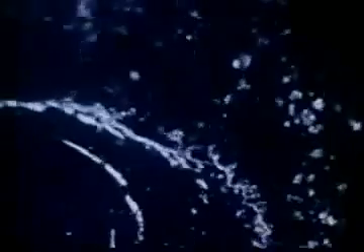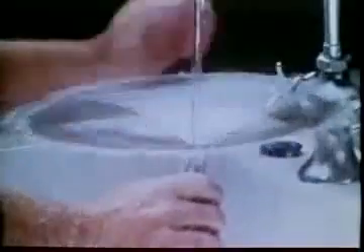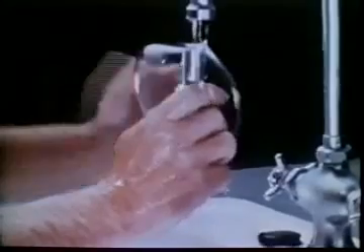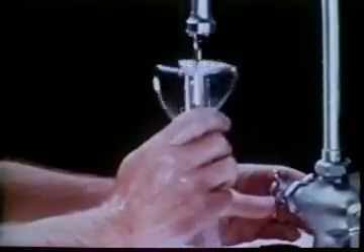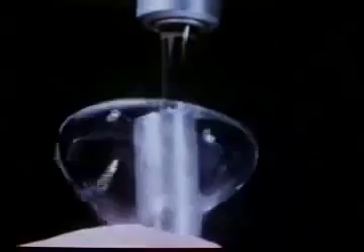When the cylinder is moved, the sheet will take on many different forms. It can even bend back sharply upon itself, apparently violating conservation of momentum. If you think about it, however, the sheet couldn't go out beyond the radius where the surface tension is equaled by the radial momentum flux of the liquid. It is at that radius that the water changes direction sharply.